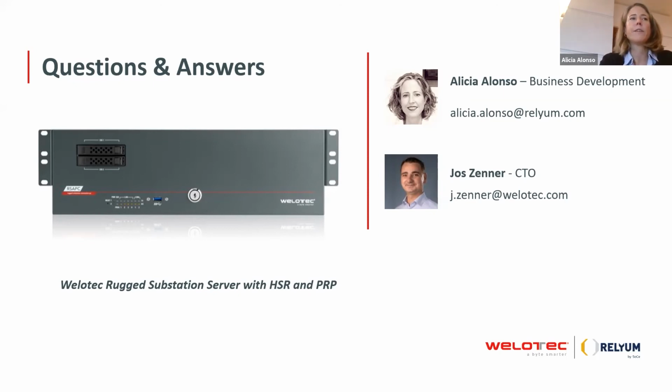And then you have the merging units and other critical elements that support PTP. Normally, the only thing is that you need an NTP server in the substation for synchronizing the non-PTP devices, and a master clock with PTP for synchronizing the rest of the devices. They are separate messages and they are completely compatible.